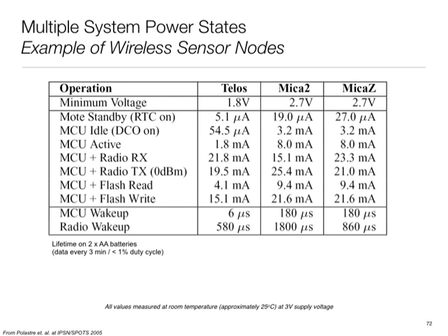So now, if you look at a complete wireless device of some form, a wireless IoT type device, you have these various components, right? You have the CPU, you have the storage part, you have the radio, you have sensors and all. And if you look at the overall totality of your platform, it can be in many states because many of them come with some pretty sophisticated finer grained control over the different parts. I could shut down the radio, but the microcontroller may be running, I may disable certain sensors, stuff like that. So you can start thinking of this in terms of these different possible states a system may be in, and then you can characterize them in terms of power numbers and all.